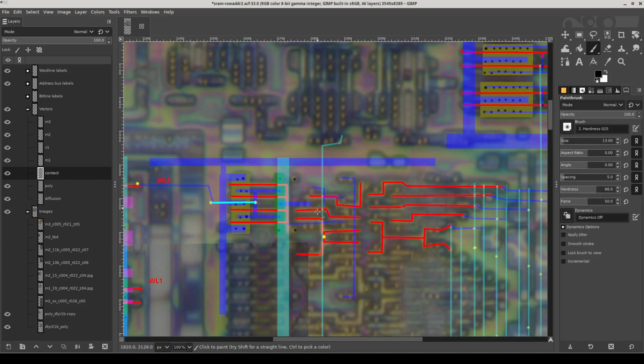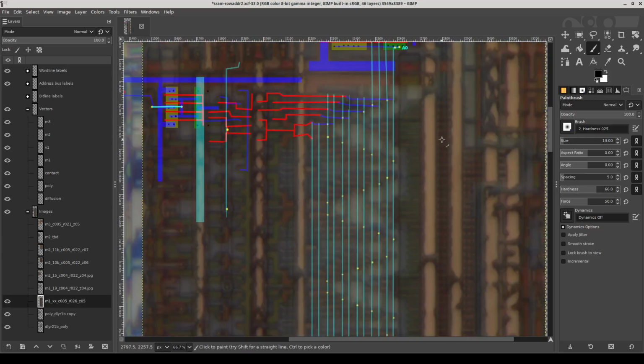And we can also see that there's this additional signal on metal 2 that is getting mixed in there somehow. This is probably a clock or a read enable or something to gate the word line, so that regardless of what's on the address bus, we don't actually want to energize the word line unless we're trying to access the bit cell. And so this is presumably the gate for that. So at this point, you may be thinking we're done. We fully understand the addressing. And I thought that at first too.